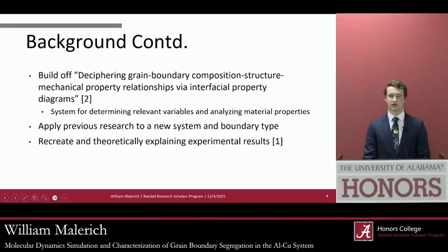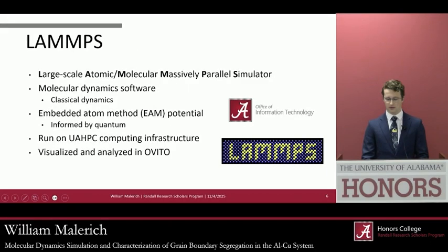So that means that LAMMPS uses Newtonian mechanics, not quantum mechanics, to simulate atoms, so it treats them as point masses with force fields around them. But those force fields are informed by the potential file, which is based off of... It's an embedded alloy method potential file, which means it's based off of density functional theory simulations, which do involve quantum mechanics, and are matched to real-life results. So it sort of simulates the quantum behavior.